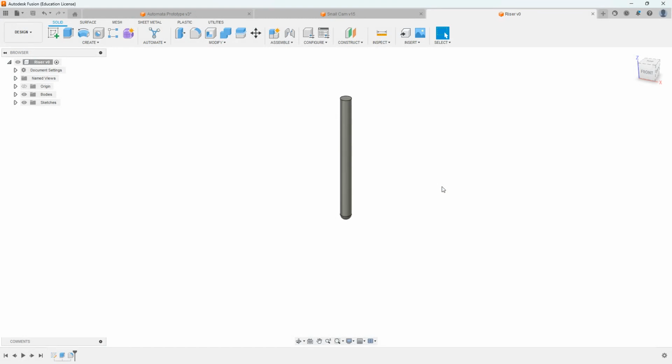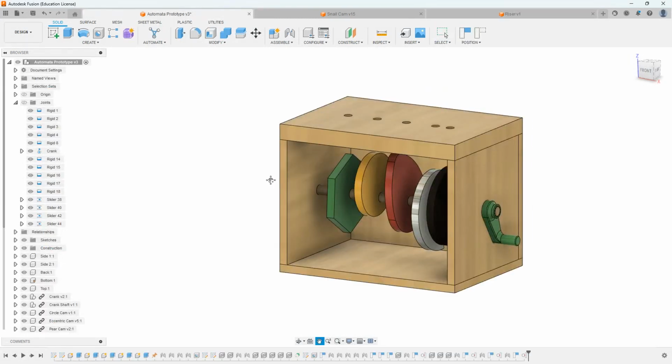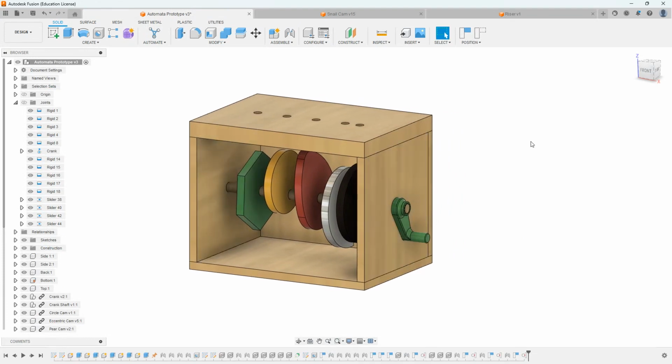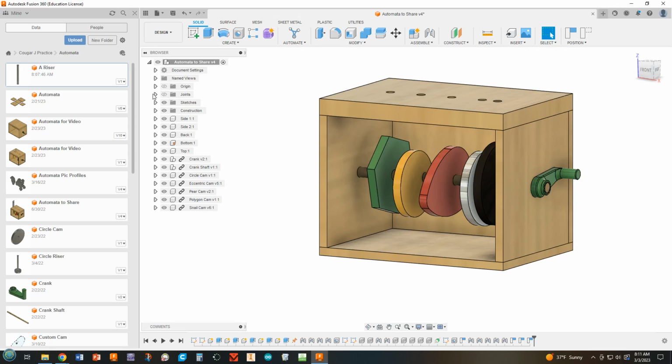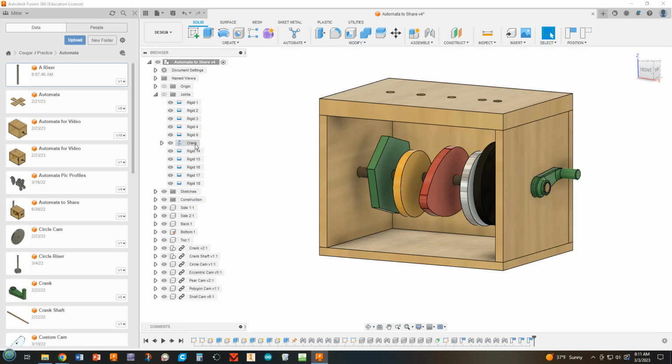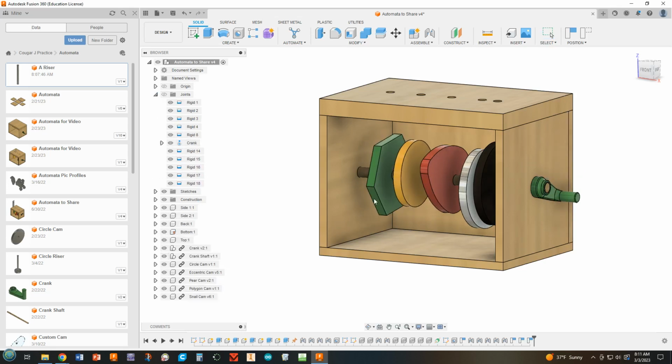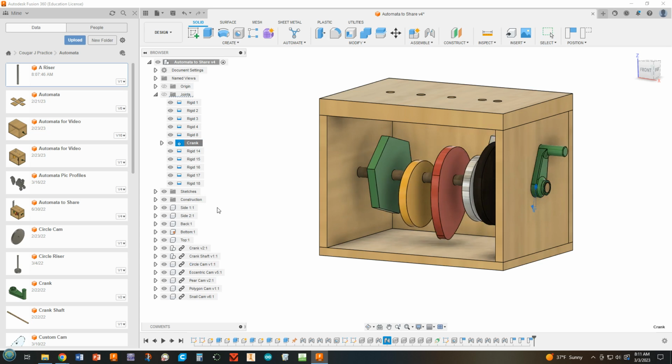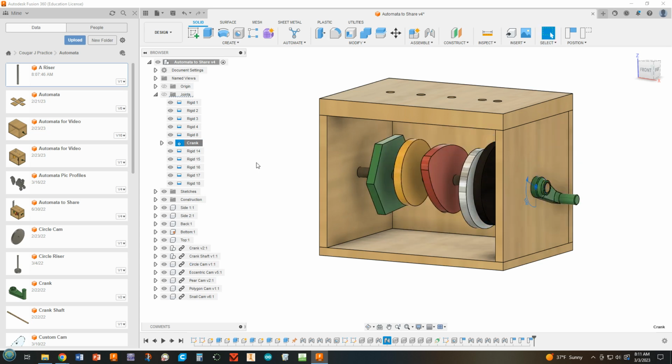Going to be doing some stuff with that later also. All right, that gets us ready to go with the rest of our assignment. So here we go. Now band joints, find that revolute joint that cranks this. You can tell by if you right click on it and animate joint relationships, it should show you what's going on. Escape stops that from happening.